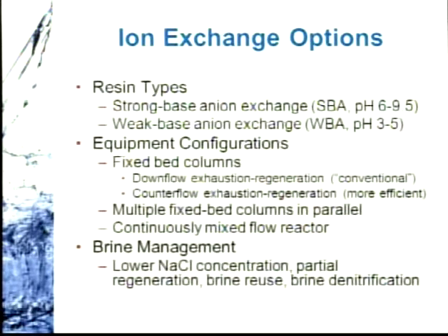Mixed or multiple fixed bed columns in parallel can improve some of the efficiencies, and we'll talk about that. And then there's the continuously mixed flow reactor, which will be talked about a bit more by the folks from Orca here in just a bit. When we come to talking about brine management, these resins are, for a strong base anion exchange resin, which is the focus of the remainder of this session, typically regenerated with a sodium chloride solution on the order of perhaps 6% at the lowest concentration, and sometimes they're regenerated with much stronger sodium chloride concentrations.